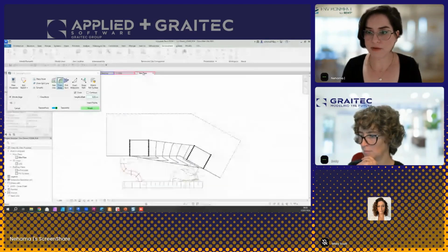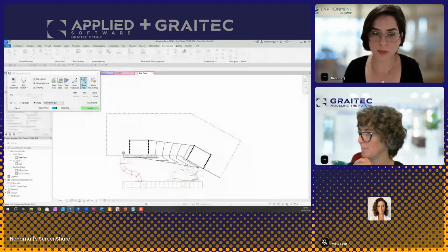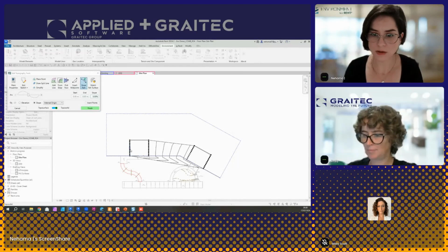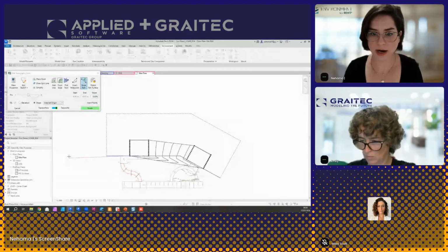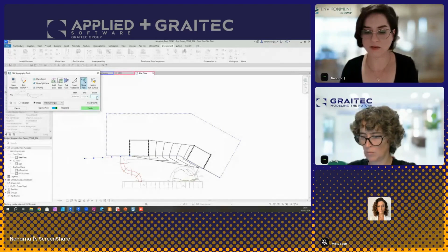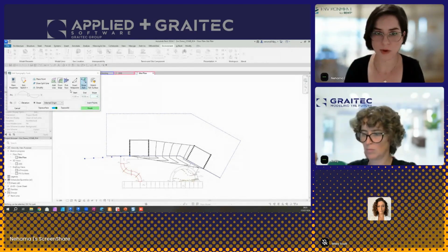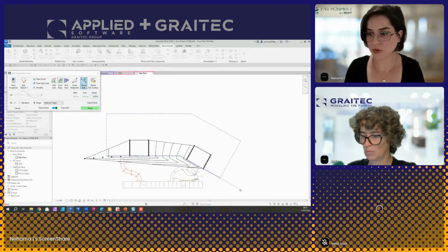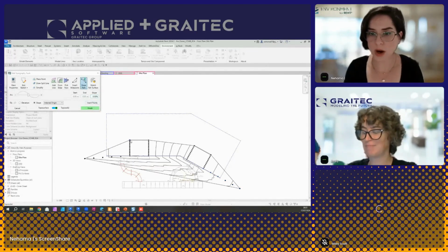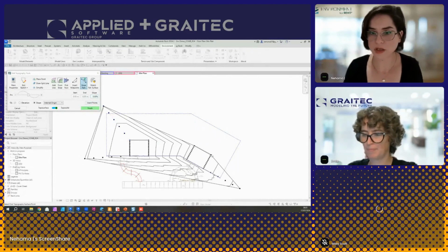And then let's go to a plan view, which is really convenient to most of us, and then use the slope path tool. So basically what the slope path tool does is I can select any point over here. Let's select this one. And then I have this line and say, all right, in this vector until this point, I want to have -2% or -1% slope. That gives me an indication of start and end. I can insert points, and I can do the same to all edges. So it's like I don't have to calculate. All I have to know is that the regulation requires me to send the water away from the building at -1%, right? So I'm going to do that.